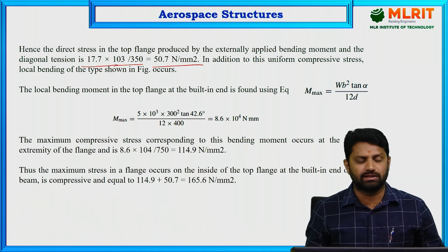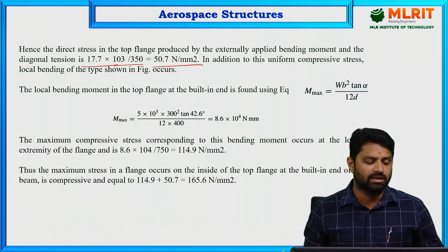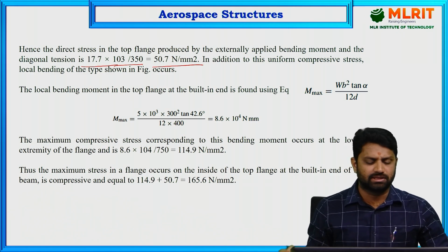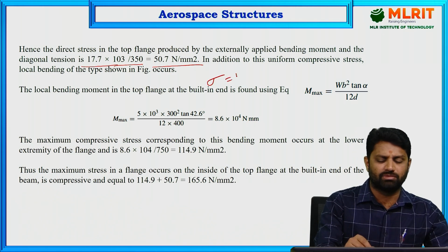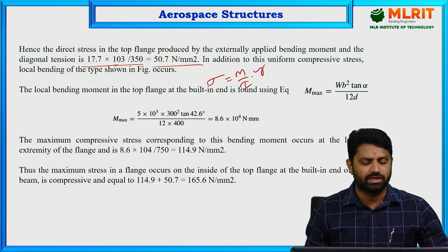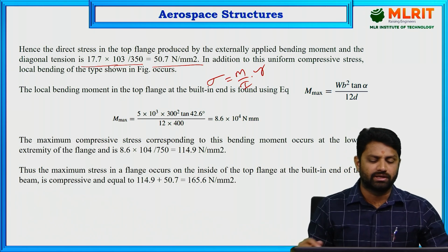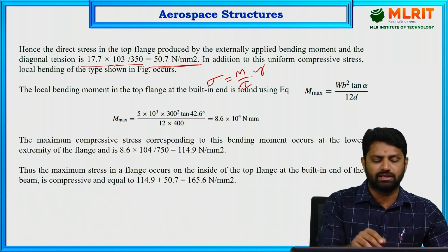We calculated the force in the top flange and then calculated the direct stress, and we know the simple formula for calculating this, nothing but sigma equals M by I into y, so that you can substitute and get the value of the direct stress.